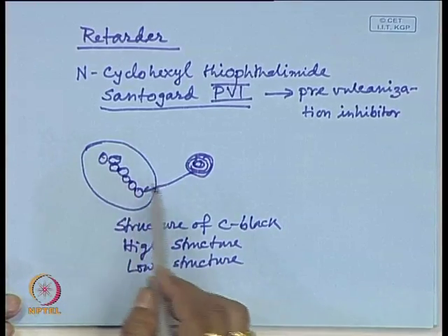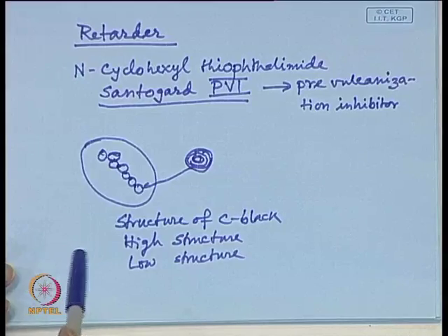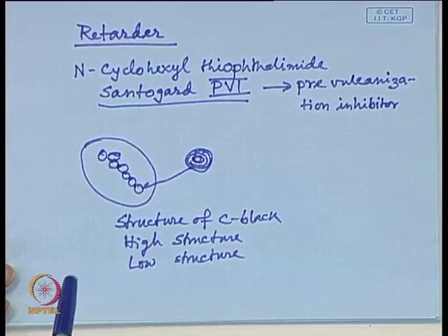Now, again they dictate the processing characteristics of a rubber compound, while carbon black is used as a filler, for incorporation and dispersion. It has been found and experimentally verified that high structure carbon black is difficult to incorporate in rubber compound, but it is easy to disperse. Please note it down. High structure carbon black is difficult to incorporate in rubber compound, but it is easy to disperse. Once it is incorporated with difficulty, then the latter part, dispersion, becomes easy.